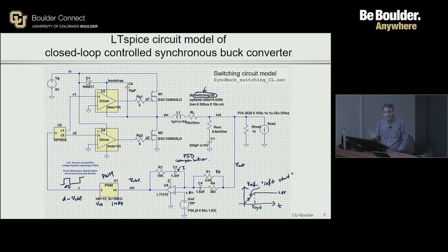Now, what do we do with that signal here? In the actual circuit, we do need another block that provides these dead times of ensuring that the two power MOSFETs are not turned on at the same time. So this block right here is called the dead time circuit. That dead time circuit splits that signal C into two complementary signals, C1 and C2, with gaps between them.